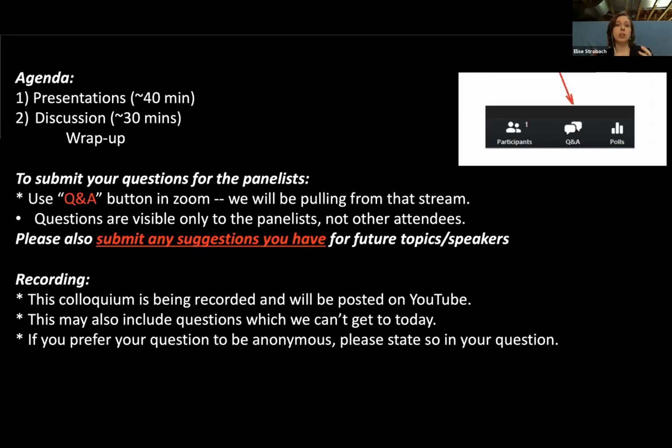It's not just once you get the product that you start it, because by then you're already behind by years. As you mentioned, with accelerated testing, it's still important to also have a full year cycle of seasons, those kinds of effects. Those can be really hard to get exactly the right conditions for. There's also intercompatibility of materials. If we put our aerogel in, let's say we didn't do a good job of making sure that the reaction when we made it was complete, it might have some hydrophobicity or some chemicals that could outgas with time, and it might be worsened by the kind of silicone it's up against in that seal.